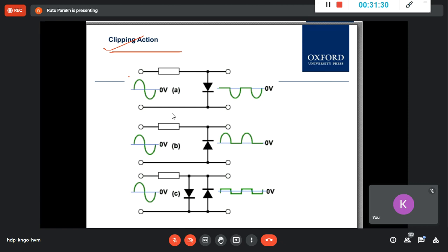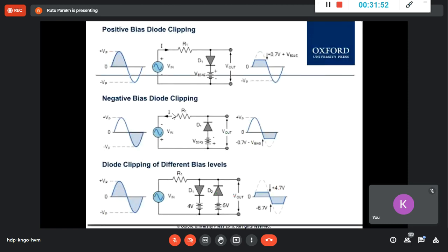There is a circuit to which you give an input and generate these shapes. There is no reservoir from which you get a sine wave, it also has to be generated using some circuit. So this kind of clipping circuit can generate, if this is a sine wave, something like a rectangular wave.